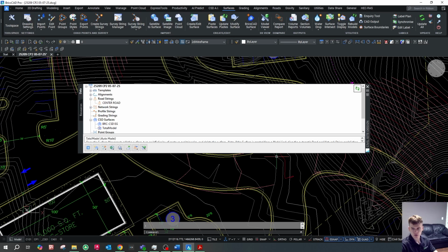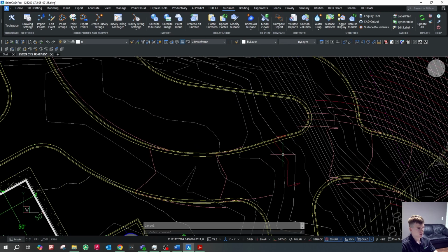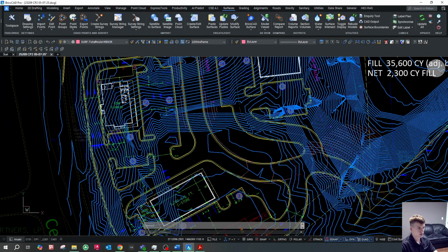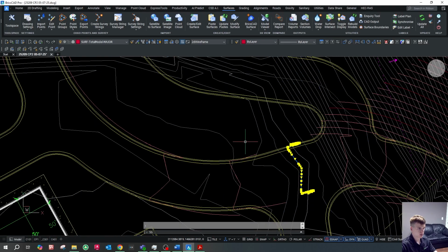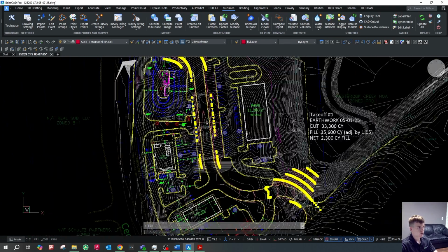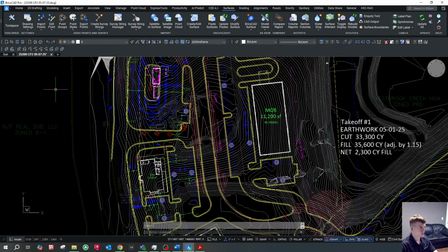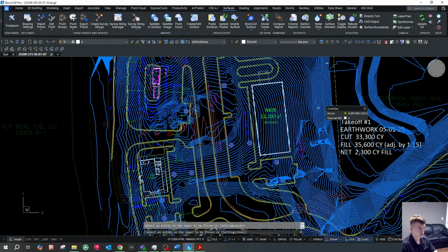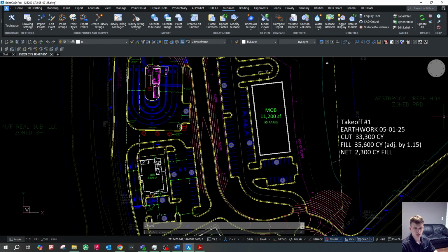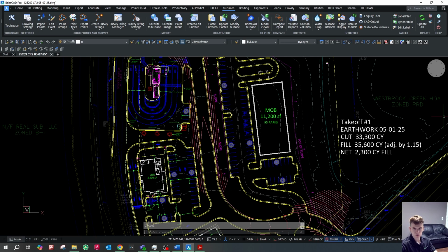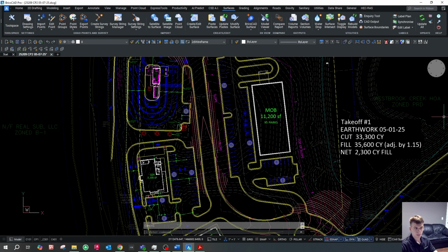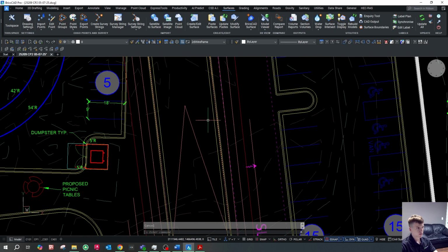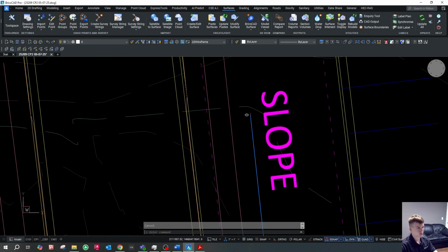We're going to drag our tool space back over. And conveniently, we now have polylines. They're also on the same layer, so we can grab all those guys. So I'm going to grab this one polyline and select, and as you can see, those are all the major polylines that got outputted. I'm just going to go ahead and freeze this existing surface once again. Freeze that guy one more time, and I'm going to turn on our existing contours layers just so we can see the existing polylines. So as you can see here, it's having this guy, which is at 980.